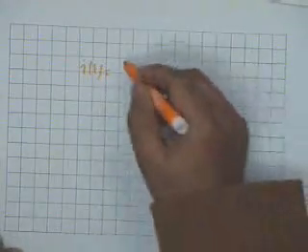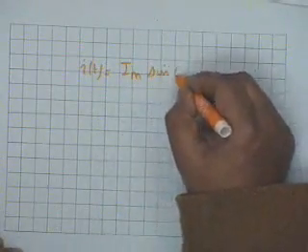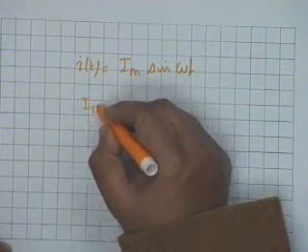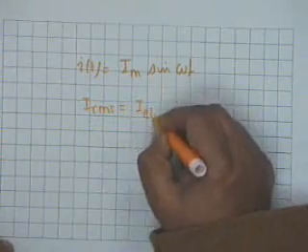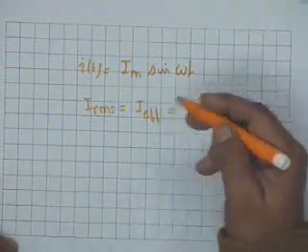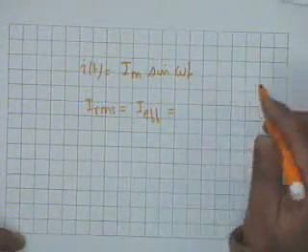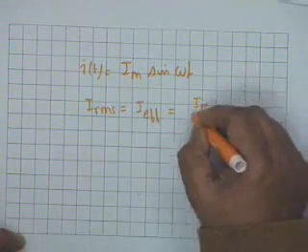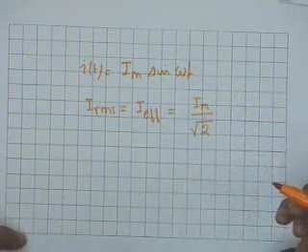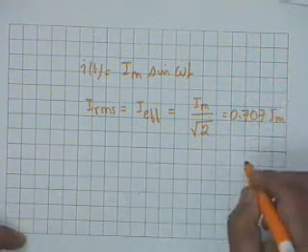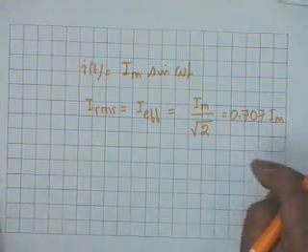For a sinusoid, if I of t is equal to I sub m sin omega t, let's drop that initial phase alpha, it's hardly important. For a sinusoid, I RMS or I effective can be shown by carrying out this integration over one time period and then dividing by capital T, taking the square root. This algebra you can do yourself. It is given by Im divided by root 2, which is 0.707 Im, that is 70.7% of the maximum value or the peak value.